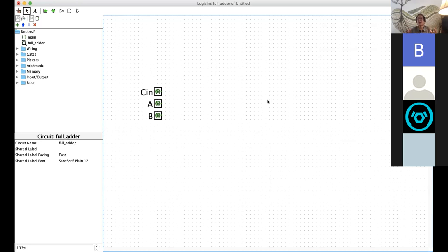You can say it's a cascade of two input exclusive OR gates, or you could make it a single 3 input exclusive OR gate, in which case you have to choose as its behavior that it will be a 1 if and only if an odd number of inputs are ones, right?